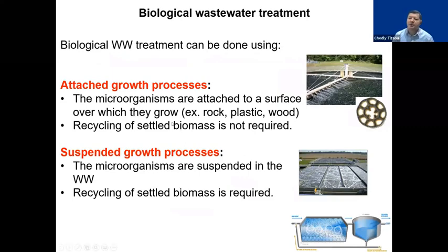I talked earlier about the attached growth processes, and that's where you have things like rocks or plastic or wood, where you have the microorganisms growing on their surface. And here is an example of a plastic material that is used to attach the microorganisms. I'm not sure if you can see my screen, but you can see there is a slight layer attached to the plastic material, and that layer is the microorganisms. Obviously, this is new technology as compared to simply the rocks.